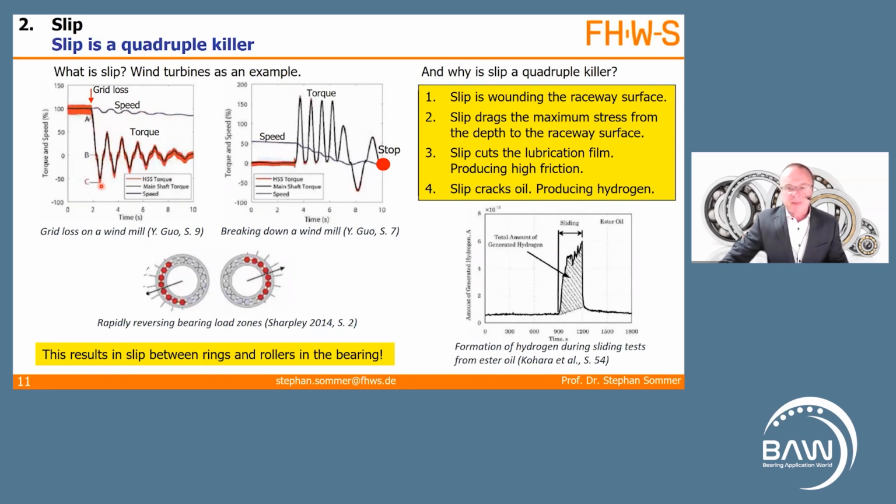But the shafts are tormented with a strongly varying torque, here up and down, until the complete wing set is fully turned out of the wind. Finally, there is no torque, but still speed. Now the wind turbine has to be brought to a stop. Brake discs are used for this purpose.